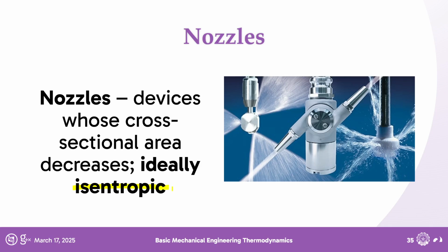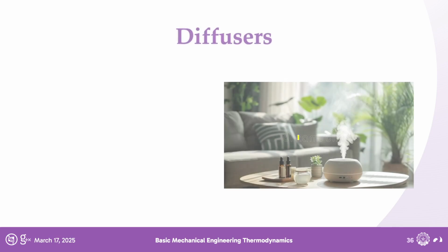So kumbaga, the liquid is traveling so fast that you're not going to remove or add heat in a useful manner. So kung papainitin mo yung nozzle mo, hindi naman iinit yung mga tubig because they're entering the system so quickly, they're also leaving it very quickly. So it won't have any effect on them. Kaya adiabatic or isentropic, right?